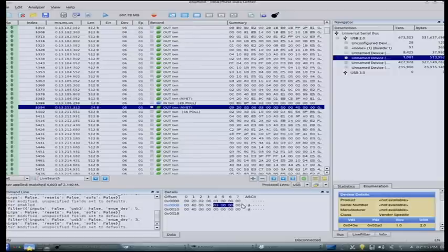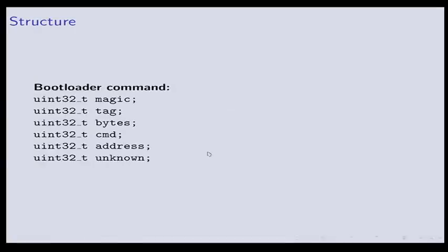Since the bootloader, you can both send it data that is part of the firmware and then tell it to start running from a new execution point. Those are separate commands. And then it's got the address at which it should place this new data or jump to. So it does all that, and that's one of these commands.